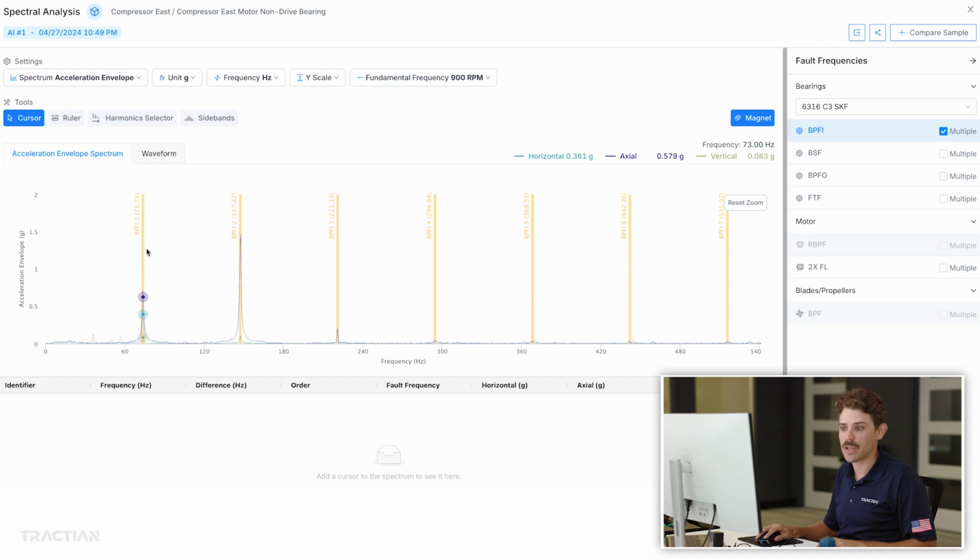And what does harmonics mean? Harmonics would mean that if I have a spall or a defect on the bottom of my bearing on the inner race, right, an inner race defect, every time that shaft comes around, it's going to go ting, ting, ting. It's going to make an impact every time it goes around its rotation. And that's what's shown here with each one of these peaks on this graph, showing that we are having some harmonics, this bearing issue is starting to get worse.